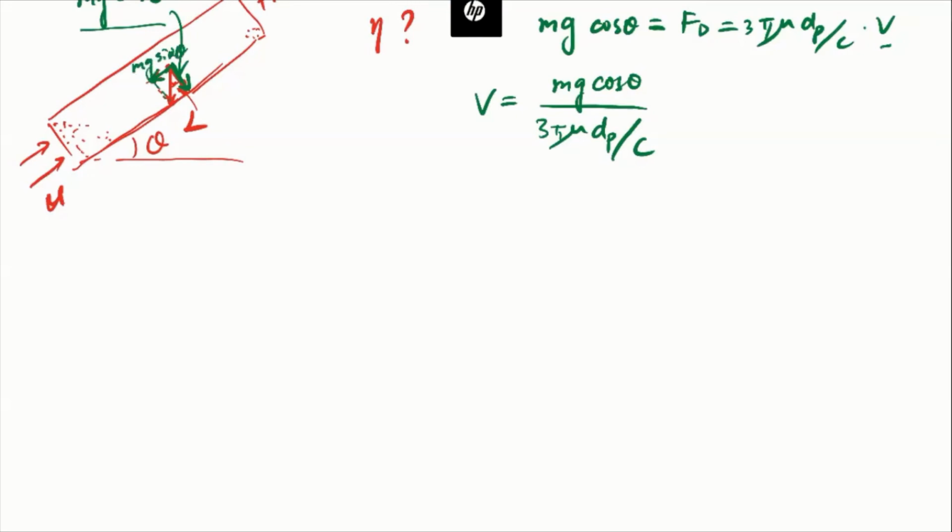So let's say if the flow velocity is 0, then the particles will just free fall. This force tries to balance with the drag force that's created by the flow. So the time the particles spend in this duct will become longer compared to a horizontal duct.